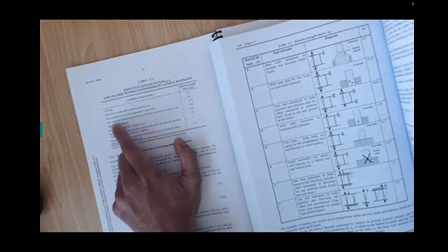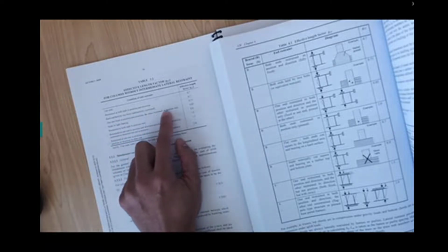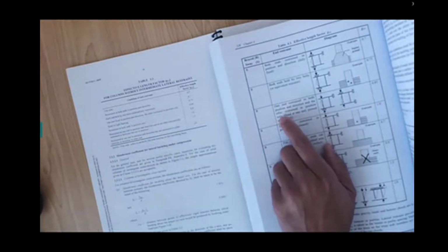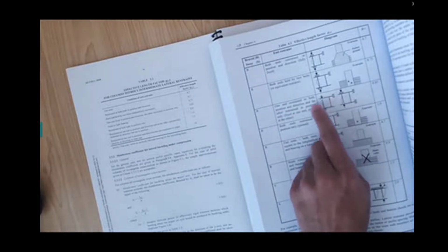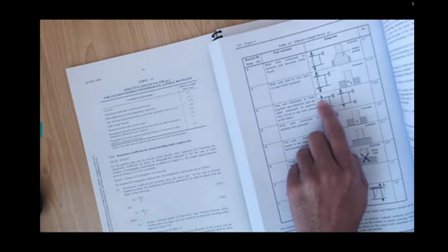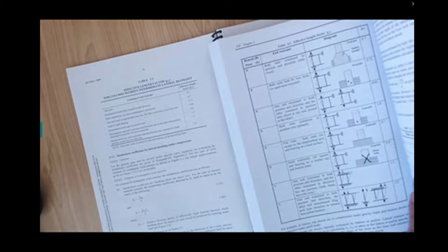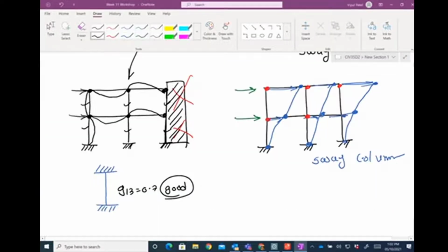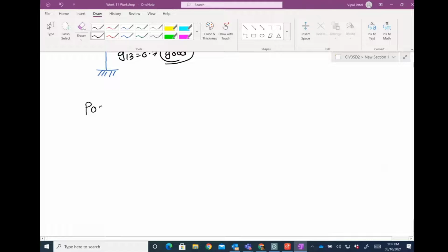Now the next case is again a brace one. One end fixed in the position and direction, the other restrained in the position only. So 0.85. It's kind of a fix and pin. So it's fixed, no matter which one is fixed or which one is pin, one of them. So one restrained in both position and direction, which is this one, and the other restrained in the position only. So position meaning, let me write it down. Position meaning displacements. The wording that they use is position. Position meaning that it's a displacement.